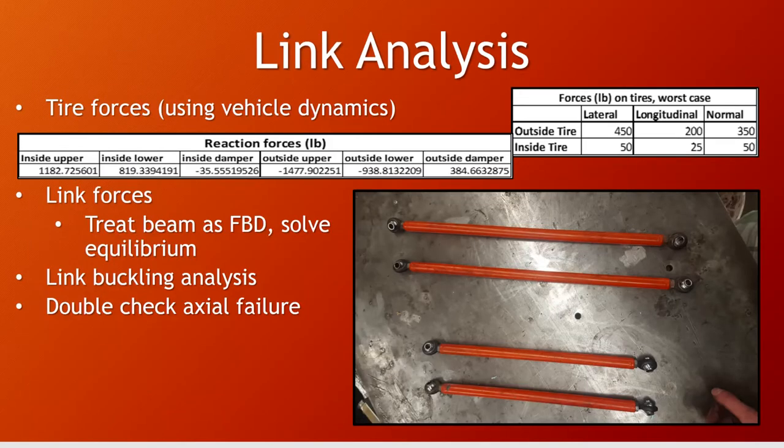All of the links will have the same diameters and wall thicknesses in this suspension. They can be analyzed for axial failure or buckling. Our analysis uses the buckling failure as our criterion because this failure will occur first and therefore must be the design parameter. The lower links are longer than the uppers, so the lower links are used as the yardstick for choosing a tube diameter and thickness. Their longer length will cause failure under a lower critical load given their identical cross-sectional profile.